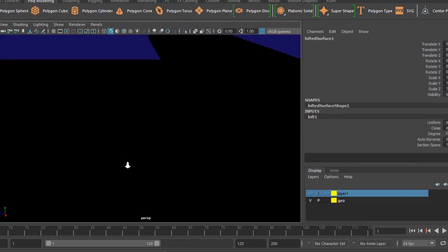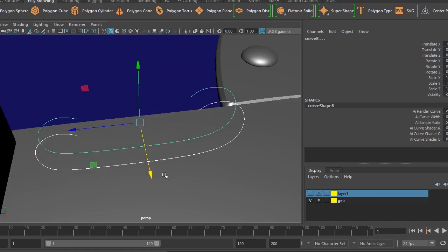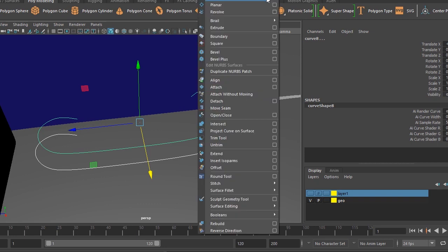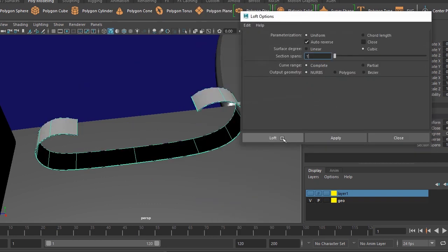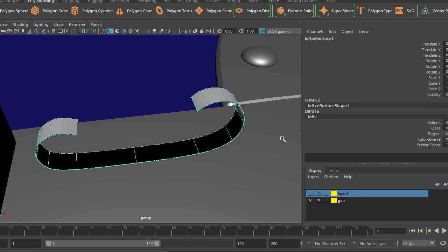So when we are lofting, this model is, you know, the NURBS output. But still, if I want to create a thickness out of it, we have a trick for that. But it's how NURBS model will work. So it's a little bit tedious, but okay, we'll try to do that way only.